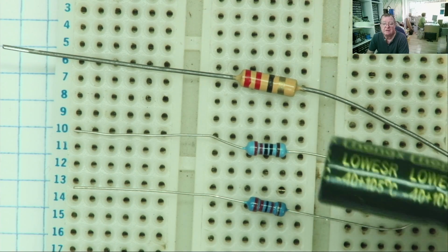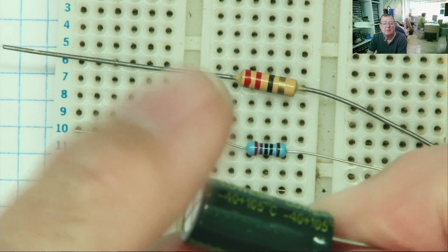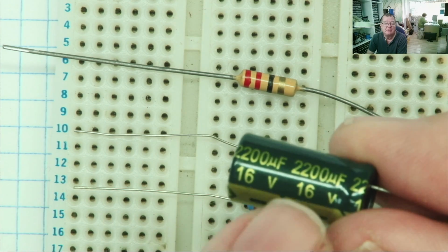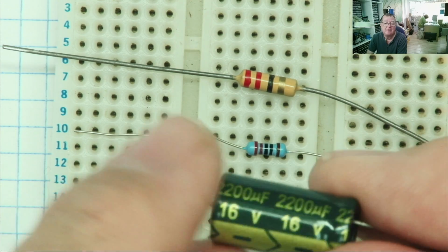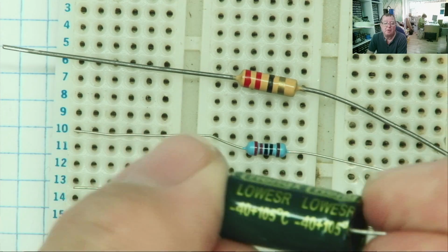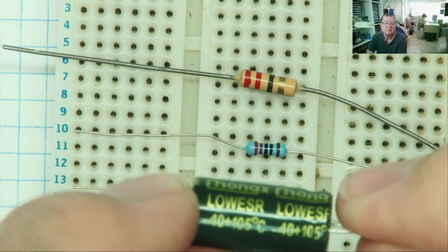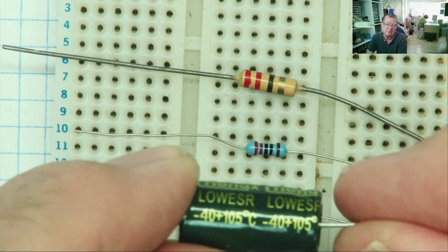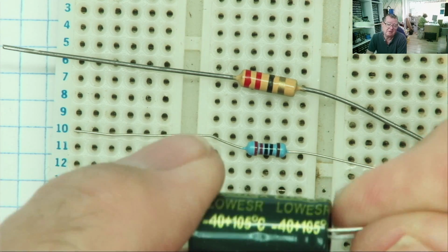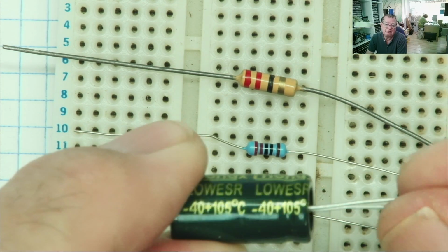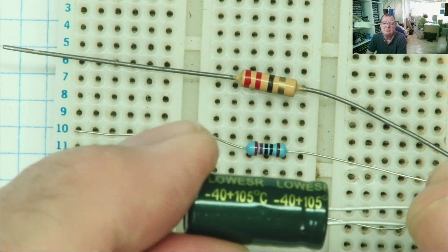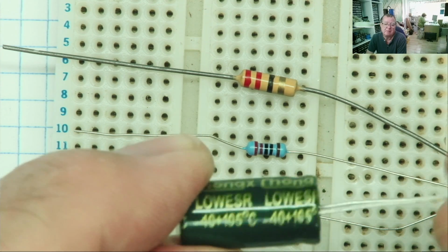And we have one more. So this is an electrolytic capacitor. 2,200 microfarads, 16 volts. So this specifies the voltage and the capacitance. This is also polarized, so this is the negative end. By default, the other end is the positive end. The brand, or ESR, we'll talk about ESR later, but not in this video. We don't need that right now. And the temperature range on this as well, the working temperature range, because this is an electrolytic capacitor, it has a liquid inside it. Therefore, as all liquids do, they boil and they freeze, hence we have a temperature working range.